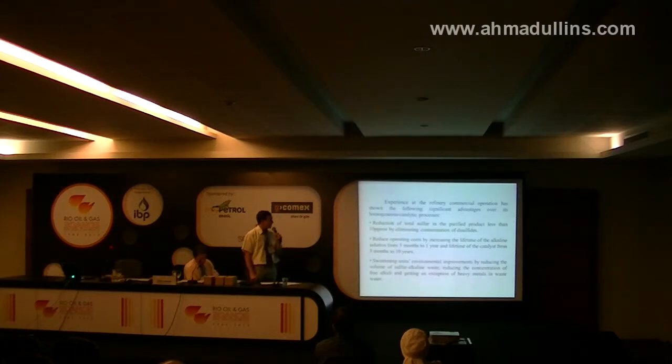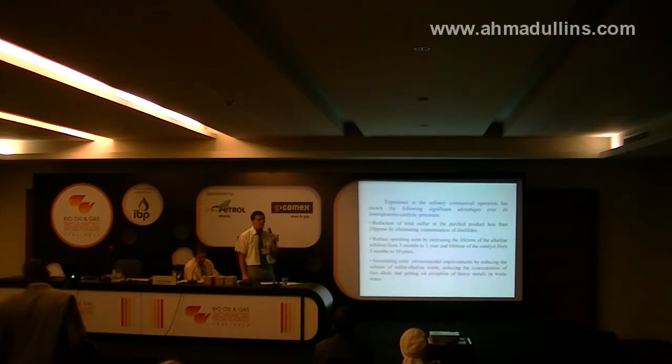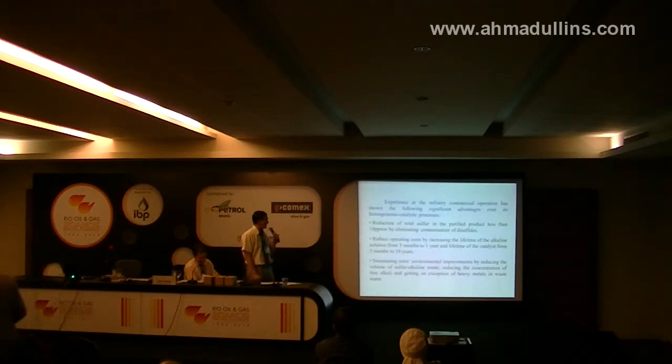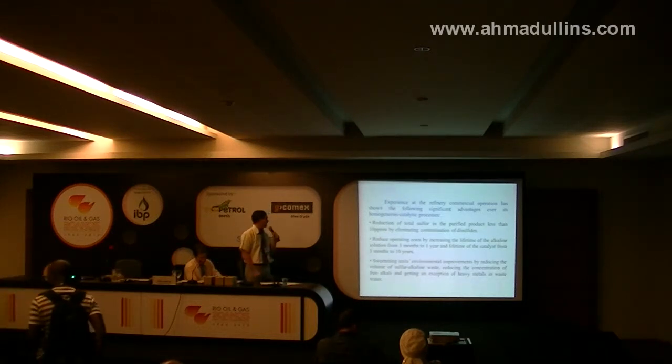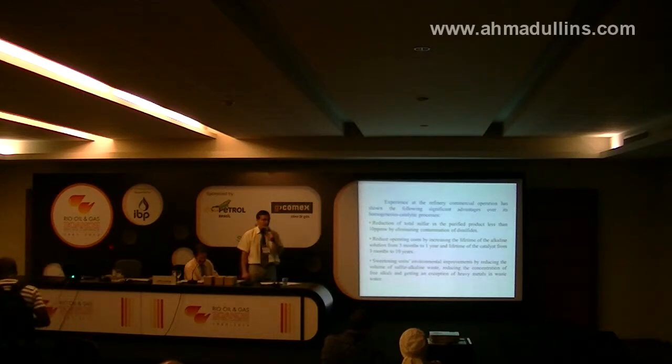Experience at the refinery commercial operation has shown the following significant advantages over the homogeneous-catalytic process. First, reduction of total sulfur in the purified product to less than 10 ppm weight by eliminating contamination by disulfides. Reduced operating costs by increasing the lifetime of alkaline solution from 3 months to 1 year, and the lifetime of catalyst from 3 months to 10 years.